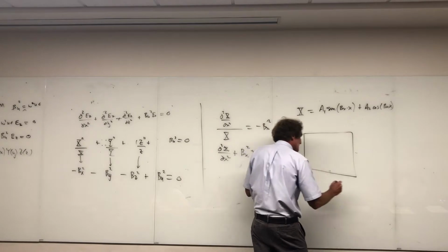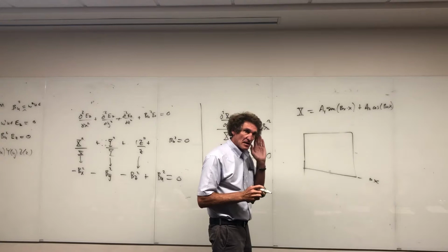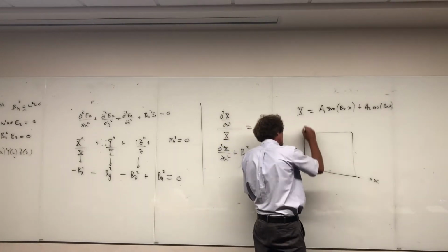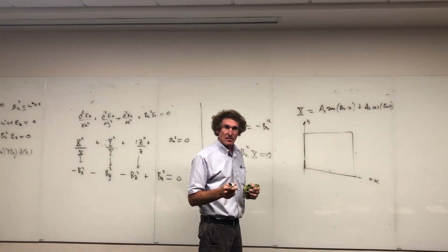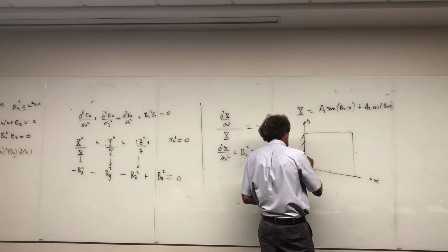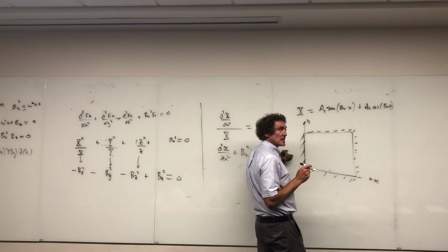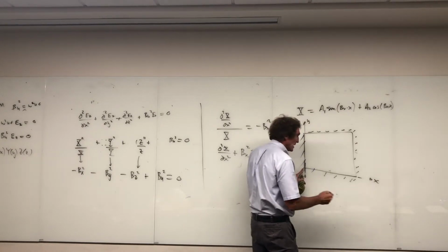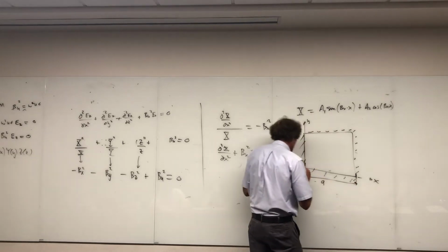and now I say this is my x-axis, I'm looking right down the cross-section now. I didn't cut this with a z-cut, right? This is just x that way, and this is going to be y. Now z's out of the board, so the wave's propagating out of the board. You all see that, everyone? Remember, those are perfect conductors here. Maybe this will help. These are perfect conducting surfaces. And I'm talking about EZ, right? Now I want you to take a look. Here's the 0 point, that's 0, 0. This dimension they call A. And this dimension they call B.